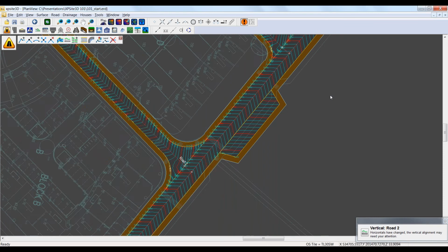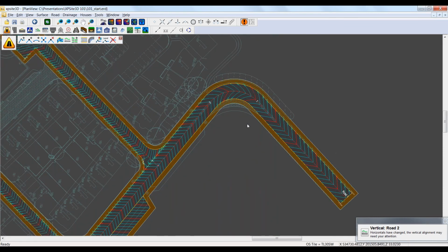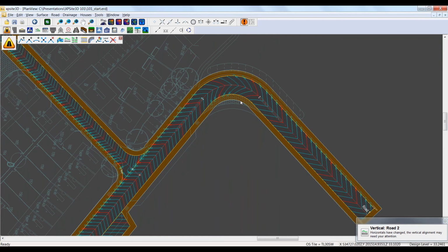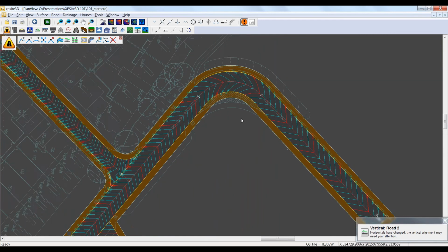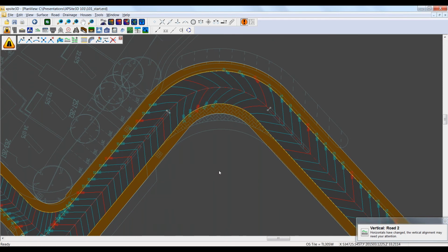Okay, the next thing I was going to do was another road widening, but this time around a curve. So the architect had decided we're going to have a little sort of safety zone or zone for bigger vehicles to turn around. So we're going to introduce that. So again, let's go for a secondary channel tool. Introduce a new one. Again, it's asking me to select which one I'm going to manipulate. So it's the front of the footway on this inside.